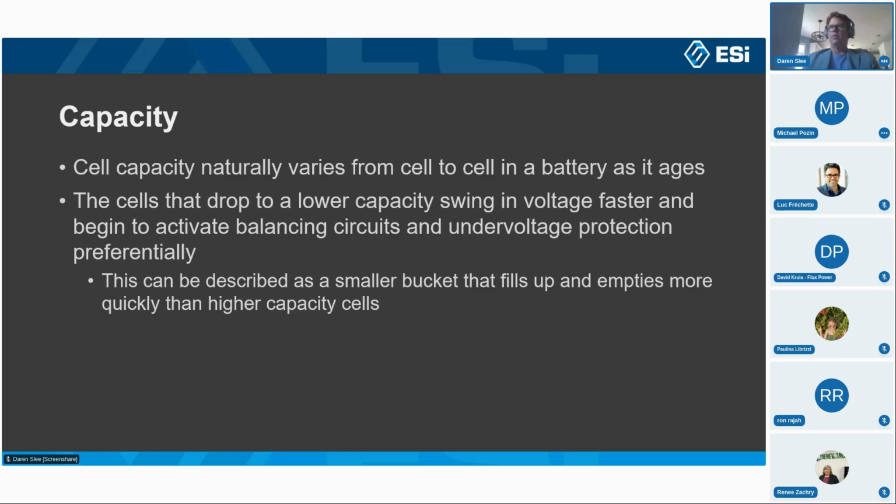And when it does that, it turns off on you because the phone says my battery is fully discharged. This is a communication issue. I'm turning off. It's not because the battery's gone below, say, 3 volts per cell, or in a cell phone, the 1 cell.